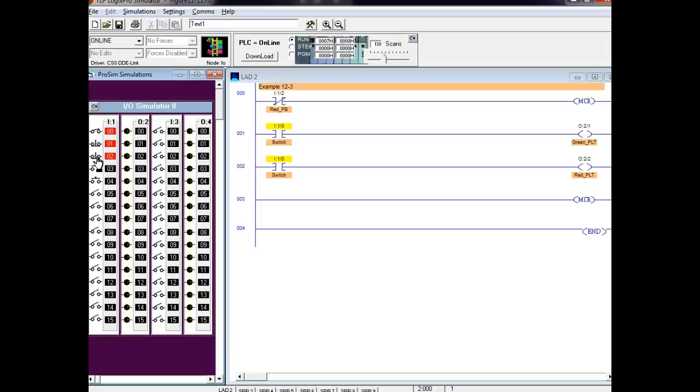Yeah, but it's not actually a stop button. When it's active, it jumps over rungs. So this looks like it's backwards. The MCR instruction will be energized and activated, therefore MCR is supposed to be used to move it to a normal. Okay. Then that is wrong. So we're using switch 2. When the MCR is activated, the instructions between MCR instructions are turned off. Yeah, so the book is wrong.